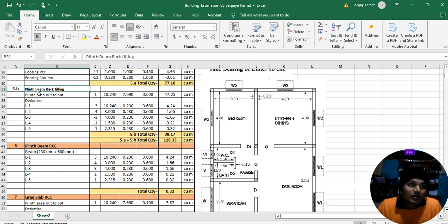Okay, plinth beam. Suppose this backfilling is coming to the ground level. From east, west, north, south, in all directions we'll keep the beam, and we'll fill there with concrete materials, up to the ground level, and from there we start to construct the room.